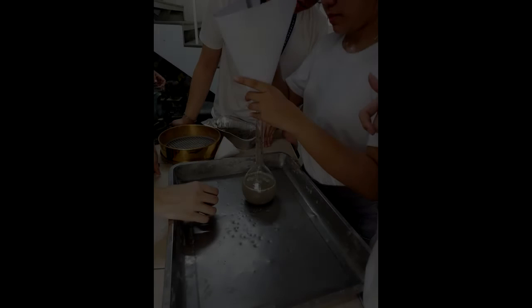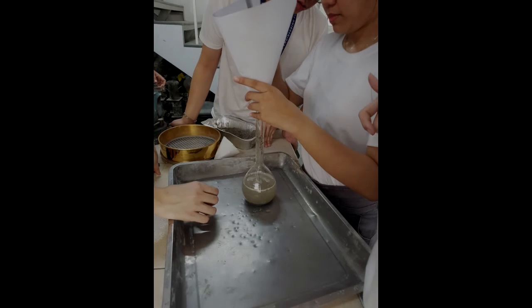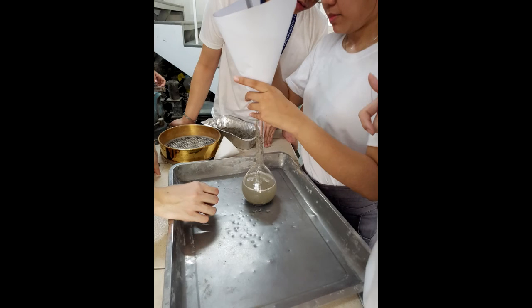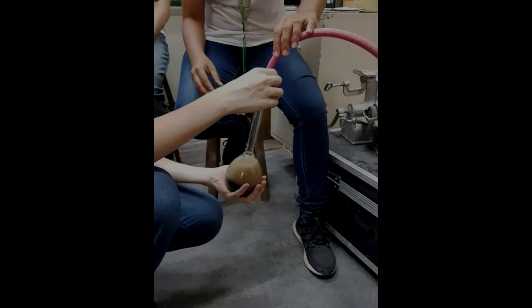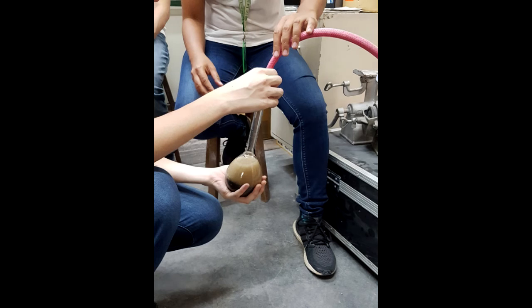For the considerations, the production of the SSD condition is important as absorbed water can affect the value of the calculated specific gravity. The sand cone test must be done correctly as it can give a false SSD condition. Additionally, during the transfer of the sand to the flask, it is important to make sure that all sand particles are submerged in the water and not on the surface of the flask.